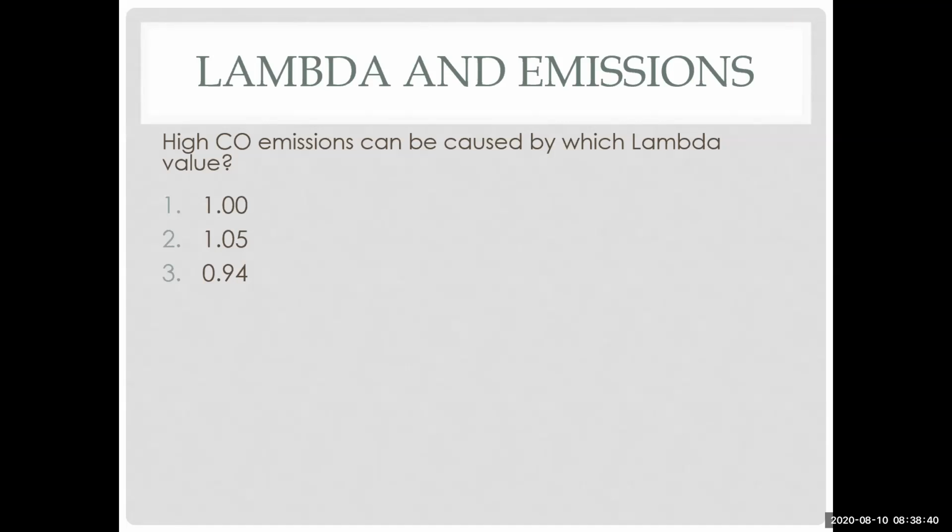Right. Okay. So, again, these are engine output emissions. What I want from my engine output is not necessarily perfect clean emissions, because as I go too rich or go too lean, I can lower either NOx or lower HC and CO, specifically CO. But what I need is the right mixture in the correct range so my catalytic converter will be efficient.